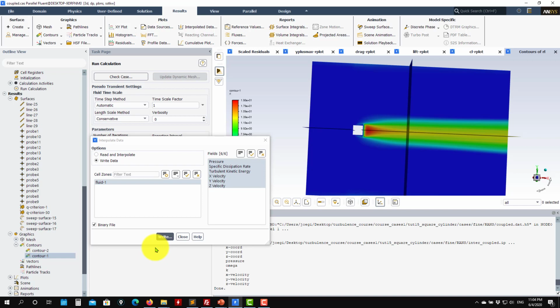We saved the interpolation file. We saw the difference. Also, we moved to the finer mesh and we interpolated the solution from the coarse to the finer. Okay, so these are basic steps that you will always need to do before running SRS simulations. Okay, then you compute the integral length scale, use the RL criterion to assess the goodness of the mesh.